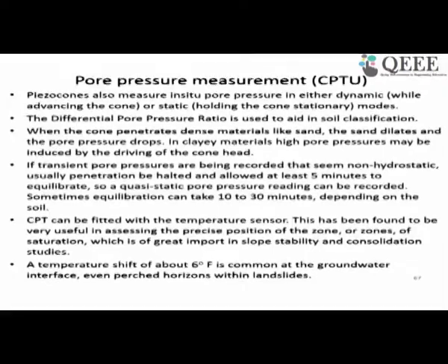So we can call that CPTU, CPT with pore pressure option, where you have included a piezometer. We also call that a piezo cone. So CPT can have additional measurement options and can be more versatile as you add additional features.